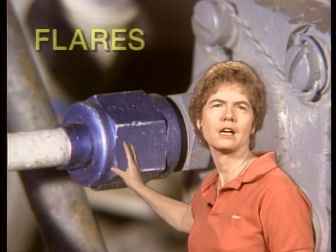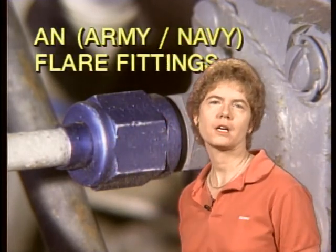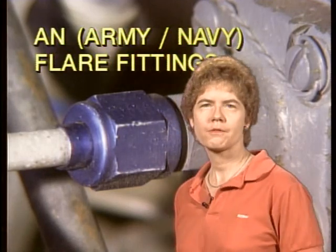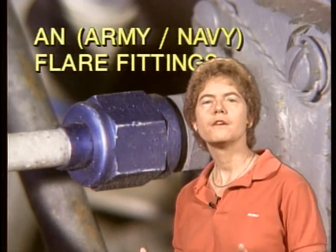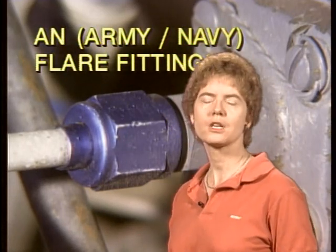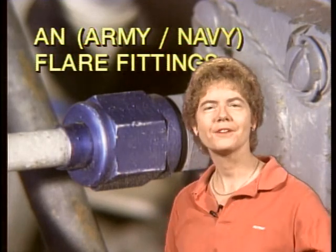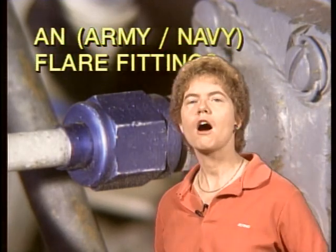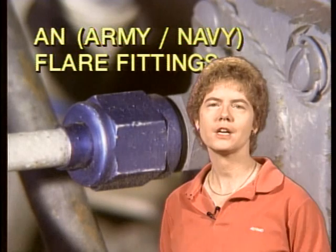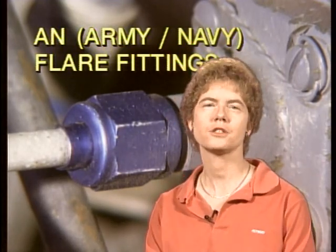And AN, or Army-Navy flare fittings, have pretty much replaced the AC or Air Corps fittings in newer aircraft. The fittings, the AN versus the AC fittings, have different shapes. Sometimes they're interchangeable, but not always. So if the FAA says to you on the test, are AN and AC flare fittings totally interchangeable? The answer is no. Sometimes they are, but not always.